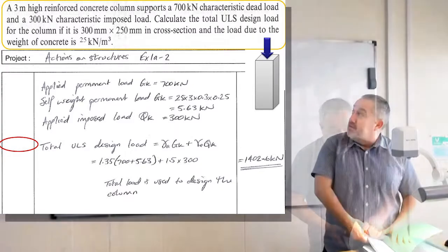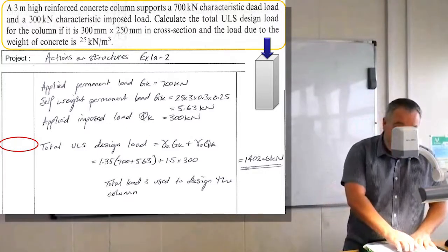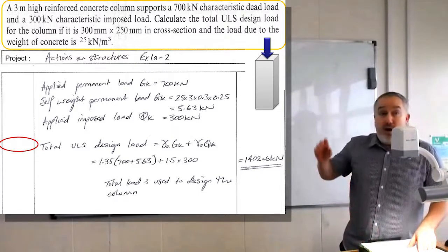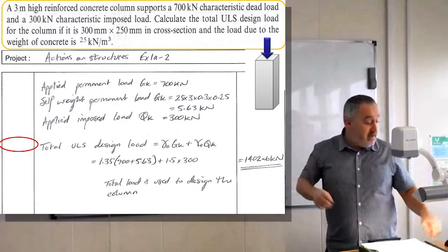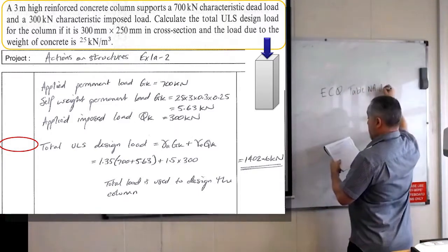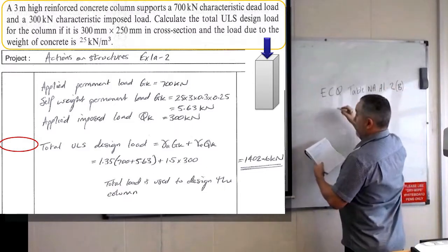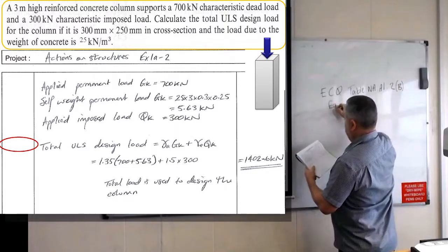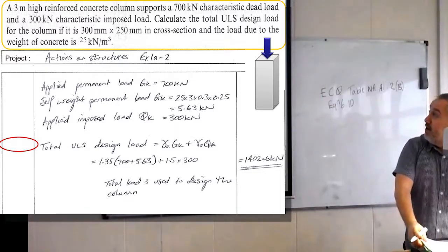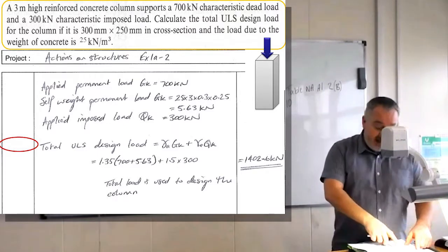So we go to our Eurocode, we go to National Annex of 1. So on the reference, on the right hand side, if you put EC0, it's in table NA-A1.2B, and we're going to use equation 6.10. So you should be writing that on the left hand side of your calcs as the reference.